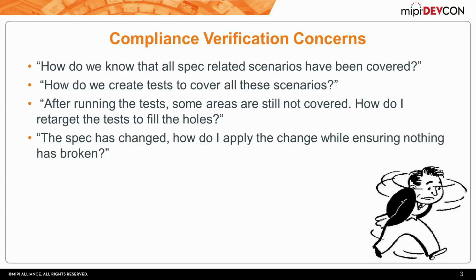So the main concerns that we have while going to do pre-silicon verification is basically deciding which part of the specs we want to check, which scenarios we want to cover, and how we want to cover them. We want to make sure that we are not overdoing it, we are not doing too many tests, and that we are not doing redundant tests for features which we are not even going to use.